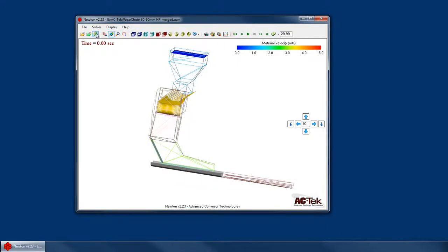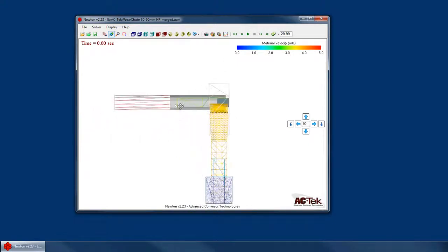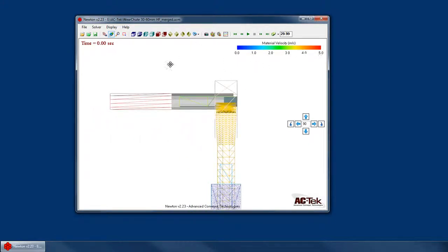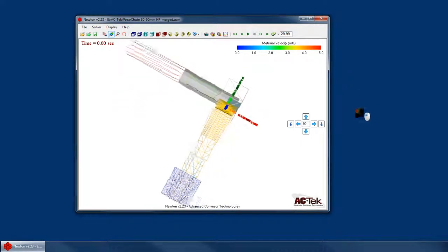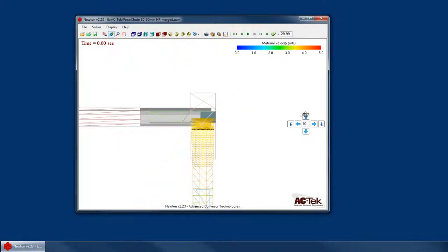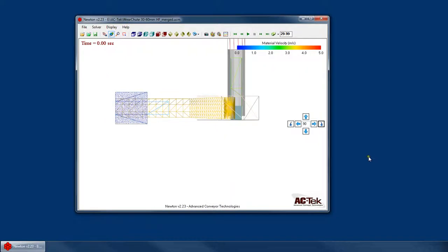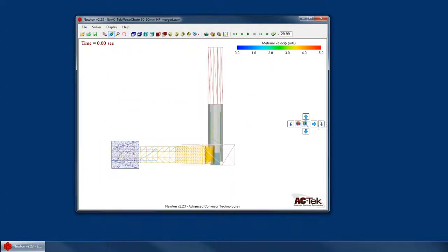So let's say I was at a top view using my top view button, but maybe I didn't want this receiving belt to be moving horizontally. Maybe I wanted it to be going up and down vertically. Well, I could try to hover here and rotate this and get it exactly perpendicular, straight up and down. Or I could simply open up my advanced orbit commands and I say, well, from the current view, I want to rotate by 90 degrees about this axis coming out of the page. And it does that. Or I could say, hey, I want to rotate by 32 degrees the other way.